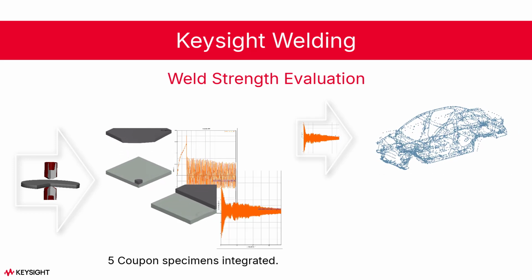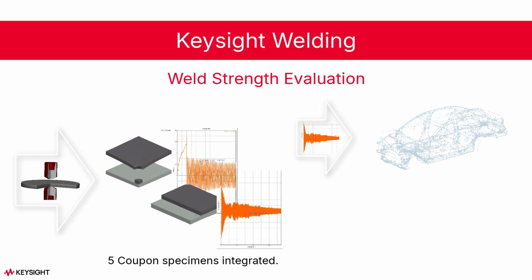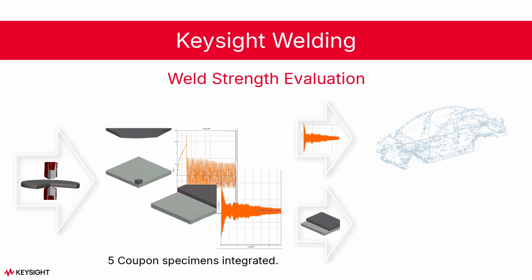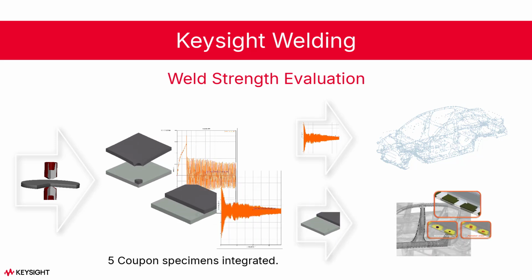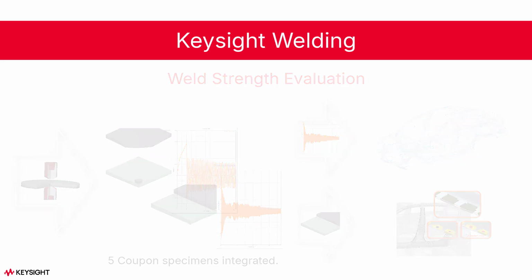When combined with Keysight's performance simulation environment, accuracy can be increased even further. Instead of importing just force displacement curves, the actual 3D spot weld models from the welding simulation can be automatically embedded in the crash analysis at critical weld locations where rupture is likely to initiate.